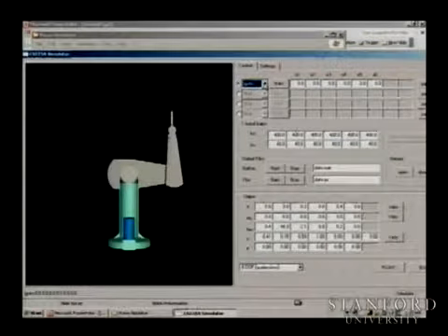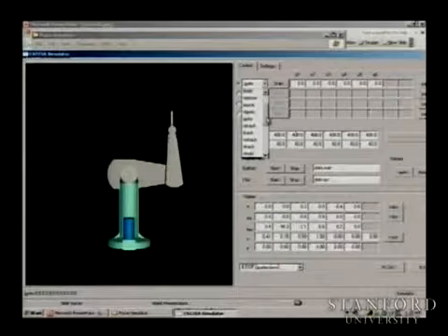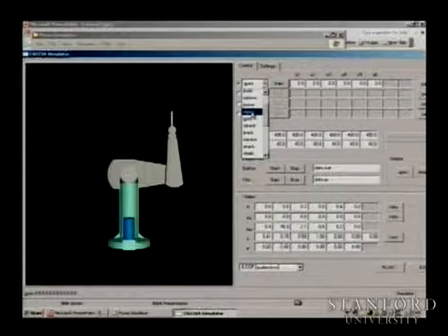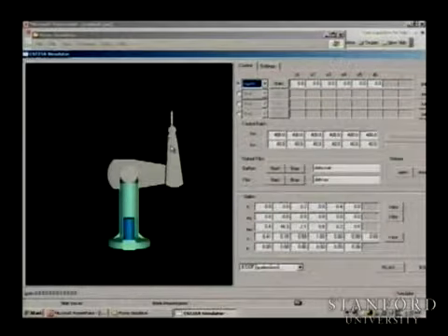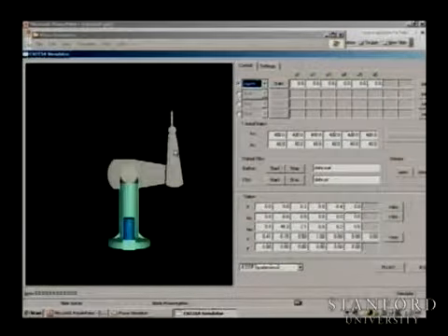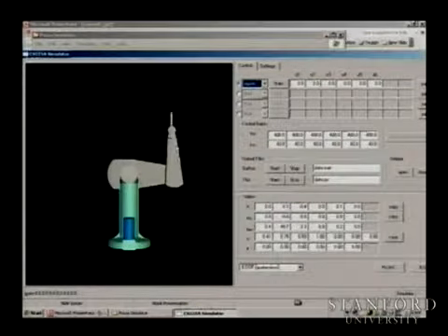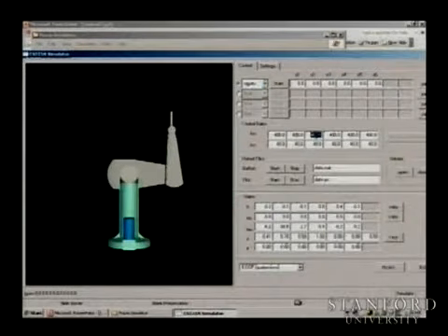But if we want to see the control without dynamics, we take probably the non-dynamic joint control, so this one. So let's float it a little bit. Actually, I can exert a little force outside and see if it can move. It's really solid. Well, you cannot move it too much. So let's reduce the gain here.